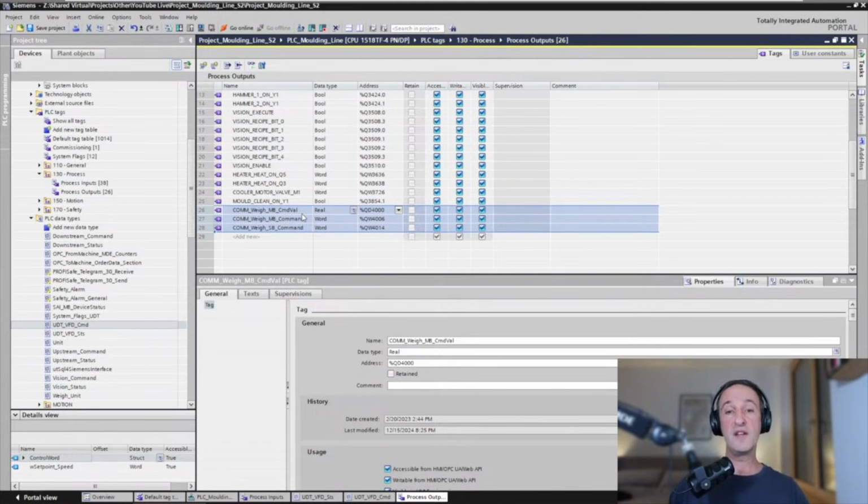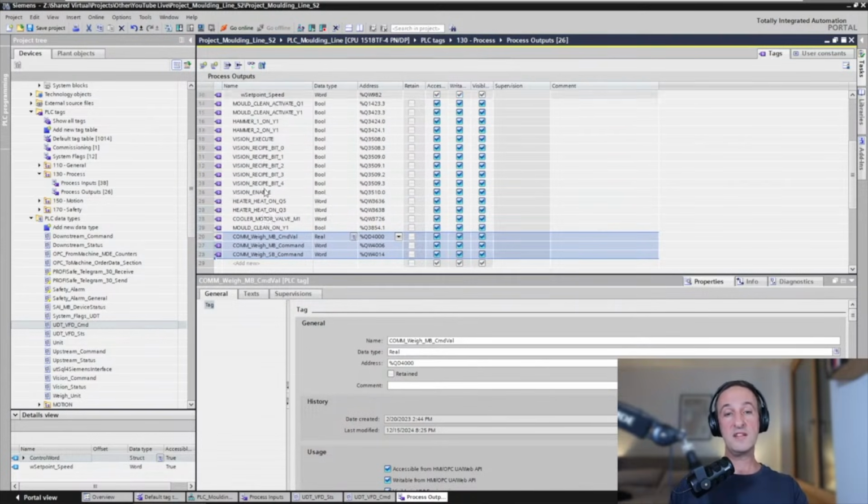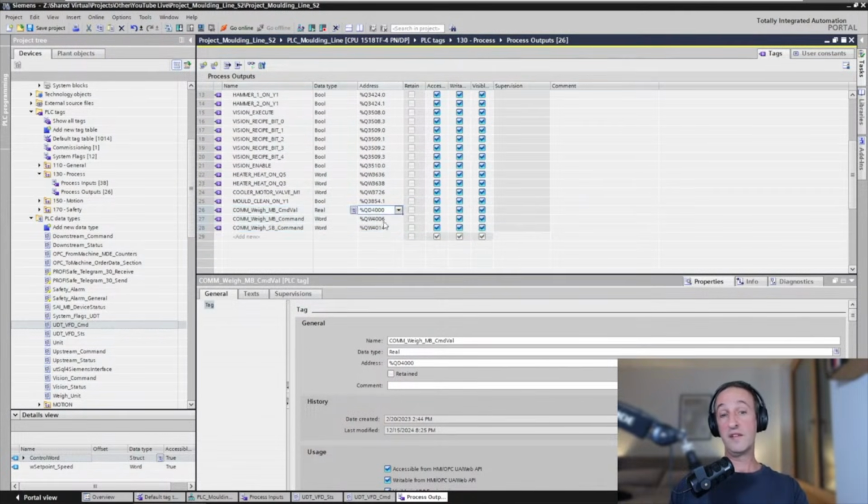If you have more VFDs, you just copy paste one and point to the start address, and you don't have the same risk of making errors. You don't have to type in 3 different addresses, you just have to type in one address. That makes it less prone to faulty programming, so you'll make fewer faults like that.